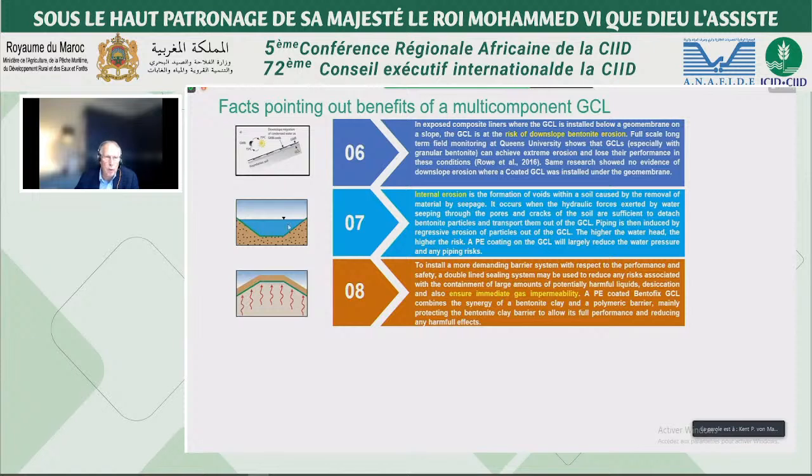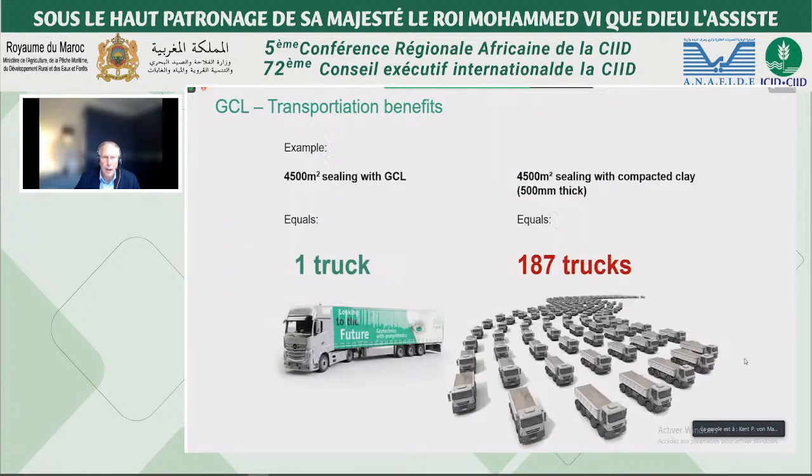You can use the geosynthetic clay liner on very coarse subgrade material. And if you should have gas, like in a landfill cap system, you can use it as an immediate gas barrier. Another huge advantage, which is more and more getting of interest in Europe, because the European Union is requesting us to look on many things, such as ecological aspects, which is the energy demand, and also the CO2 emission,